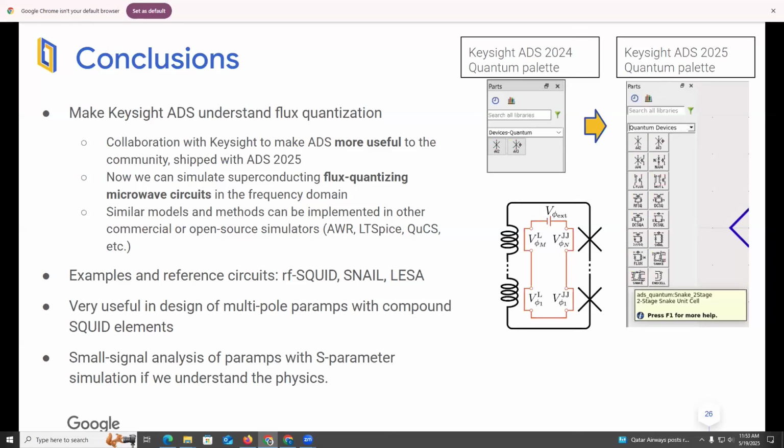The components that we've used are just linear components that you have in your simulator for sure, and controlled sources, which your simulator probably has for sure as well. And the only thing that you need to add to that then is a symbolically defined nonlinear device or a Y matrix.